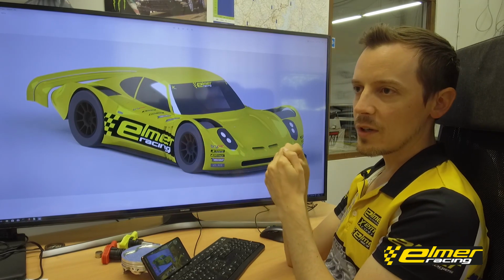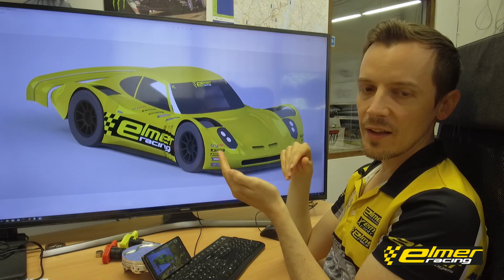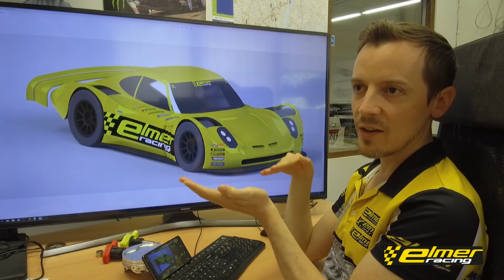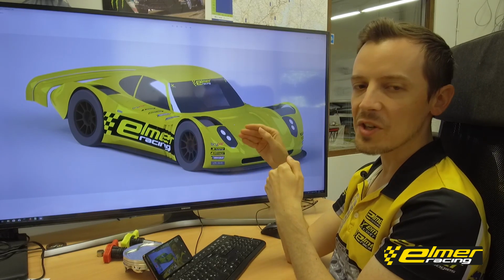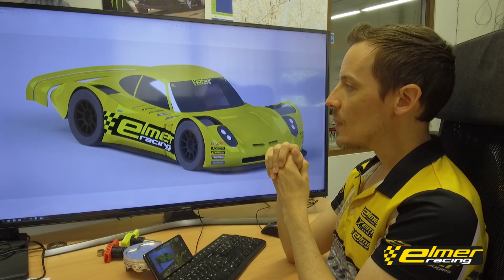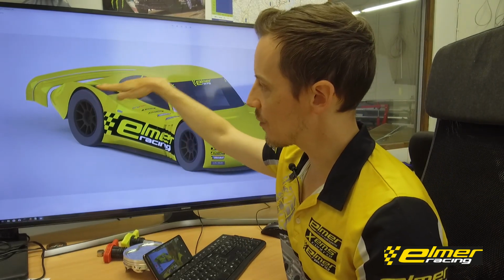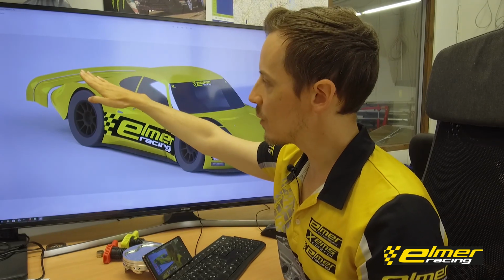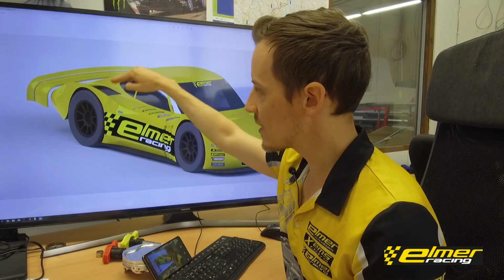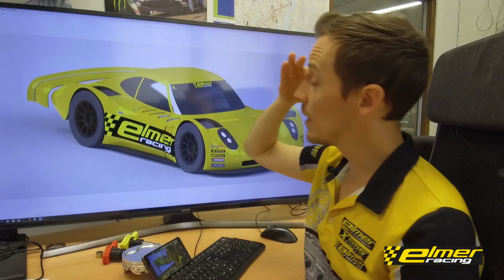When you speed up a flow relative to an object, the surface on that object sees a lower static pressure. So with typical wings, you get a higher flow velocity on the bottom side of the wing, and slower flow velocity on top, and also a deflection of the airflow with the rear wing.